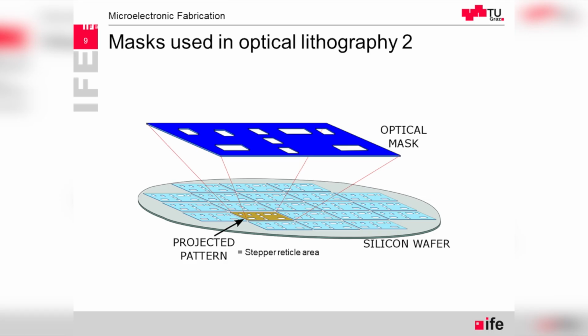And then we have the light from the photolithography scanner, which is focused on a single reticle area. So the mask doesn't cover the whole wafer, but just a certain area. Of course, the mask is also much larger than this area. Like that, we are able to produce the mask that has to produce later much smaller features on the wafer. And the process is going through scanning. So that's also a little bit of a bottleneck. That takes quite a long time, the whole process of photolithography.